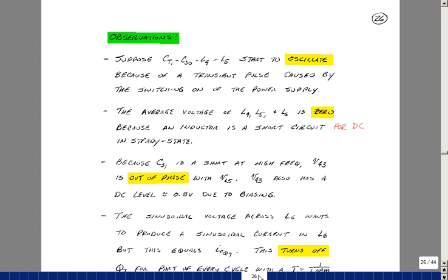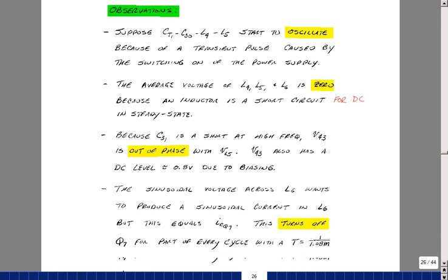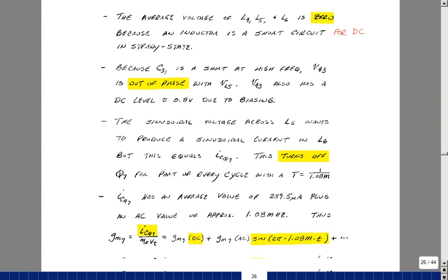So take a look at page 26. Now, some of the things that we've already mentioned. The oscillation is occurring from the transformer T5 with the variable capacitances that are there. We saw that the average value of the waveforms was 0. That's because an inductor is a short circuit for DC. There's also a phase change with the voltage across the resistor R33 because of how the dot notation is. And then we saw the transistor being turned on and turned off, but it's done at a frequency that matches the resonant frequency of the primary side of T5.